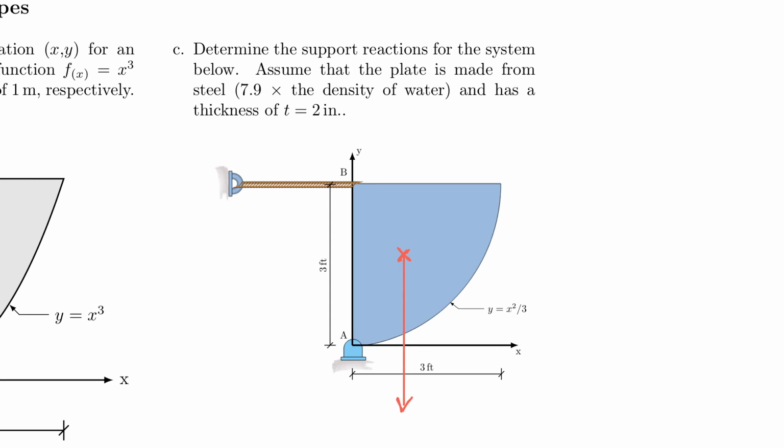And so once you would know what the force of the plate is, so I'm going to call that force F plate, and you were to know the distance that the centroid location, or the center of gravity in this case, has to the y-axis, right? Let's call this here x bar for now. Then I could actually calculate all my support reactions.